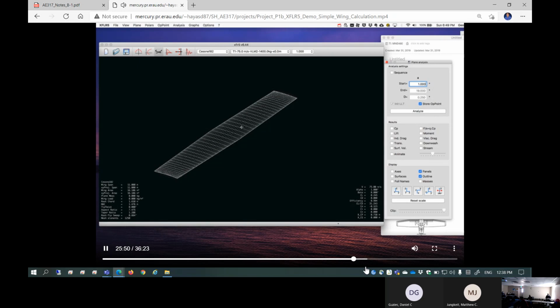So for each of these, once it's done with the inviscid solution, it will come back in and say, okay, the lift coefficient of this strip is, say, 0.31, and the Reynolds number is 7 million. And then it'll go to XFOIL and ask, for a lift coefficient of 0.31 and a Reynolds number of 7 million, what is the drag coefficient? Whatever the lookup table says, it'll apply that to this strip. Then it goes to the next one and does the same lookup. CL is varying, Reynolds number is varying, so it has to do this for each of these strips and gets the drag coefficient for each strip.